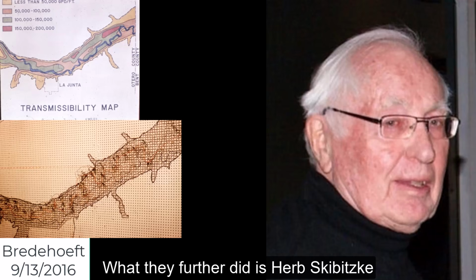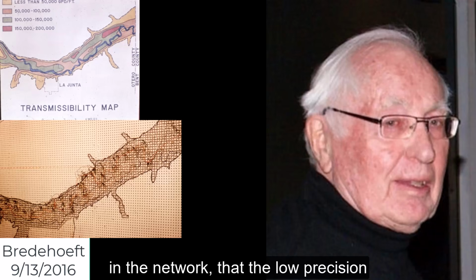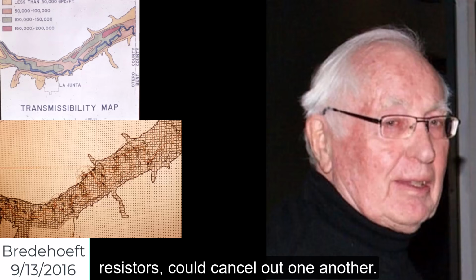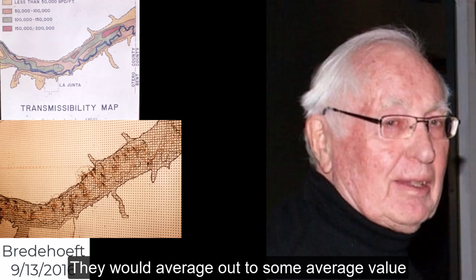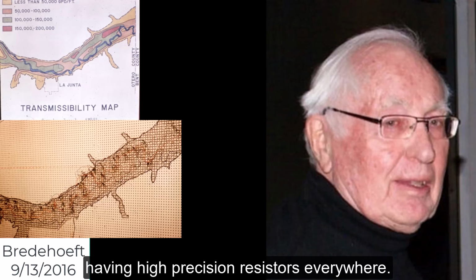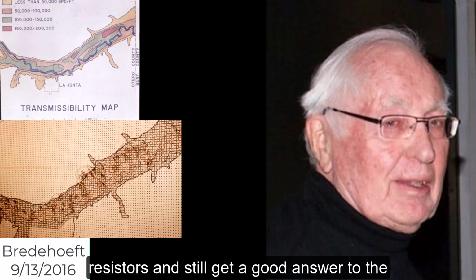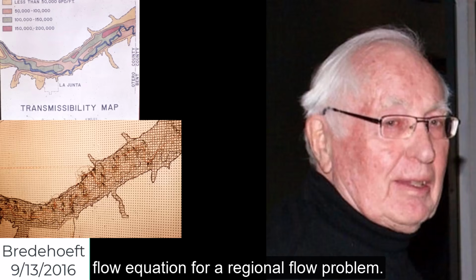And what they further did is Hsieh realized that if you used low precision resistors in the network, that the low precision resistors could cancel out one another. They would average out to some average value, and so you wouldn't have to worry about having high precision resistors everywhere. You could build a network of low precision resistors and still get a good answer to the flow equations for a regional flow problem.